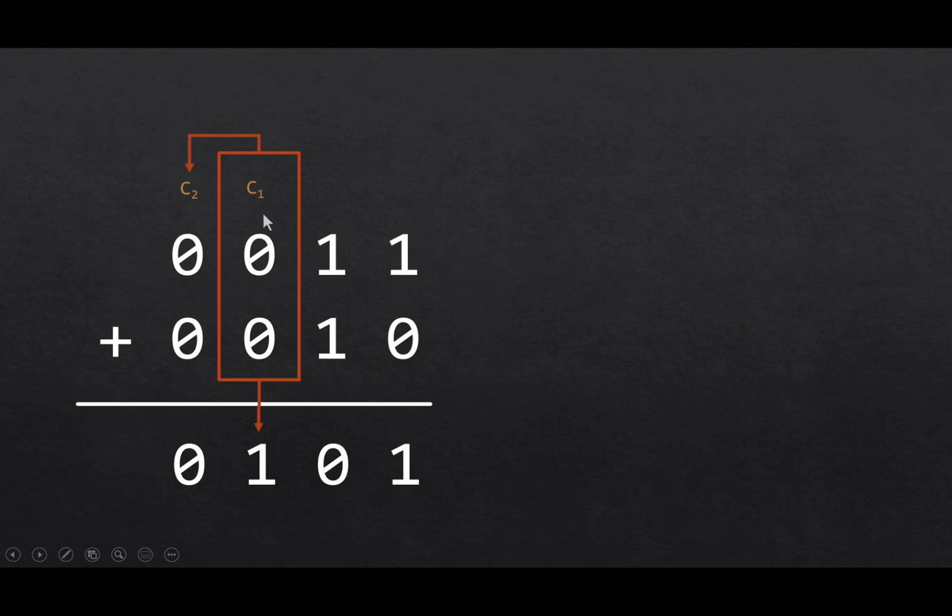And again, we just use another full adder to take the carry from the previous column's addition, and then add these two columns. And in this case, for example, adding this has given us 2, and so we've gotten a 0 here, but we've carried 1. So now we have 1 plus 0, which gives us 1, and then we don't carry anything.